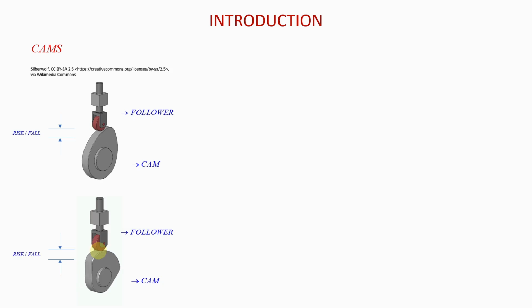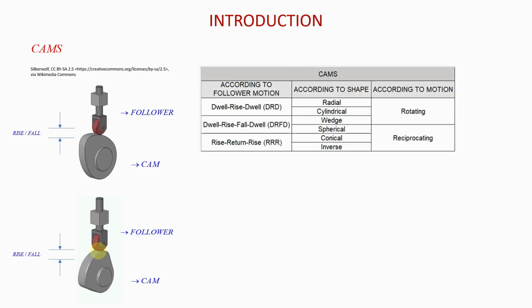And so depending on the type of mechanical application you have in front of you, you can design a cam system to allow you to actually achieve that. Okay, very, very important. But what I want you to see at this point is that the motion of the follower is essentially dependent on the shape of the cam and also the angular velocity of the cam, because if we spin the cam faster, the follower will also move faster. Okay, very, very important.